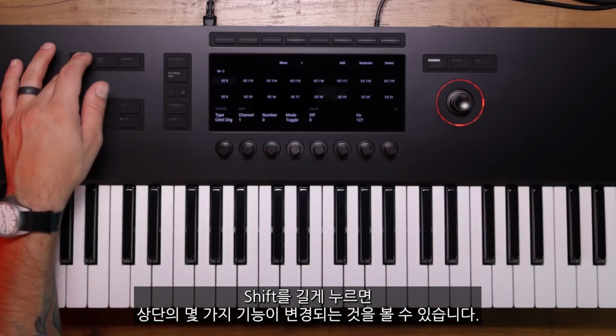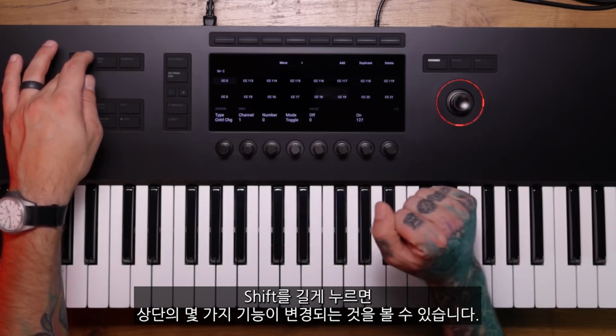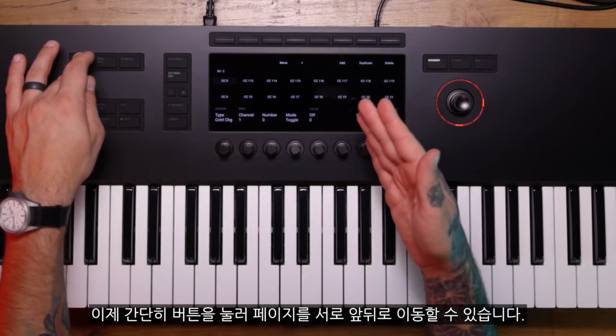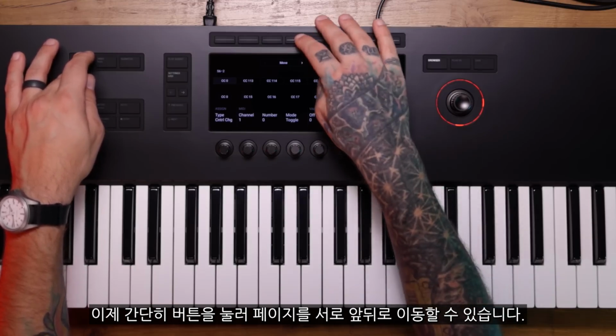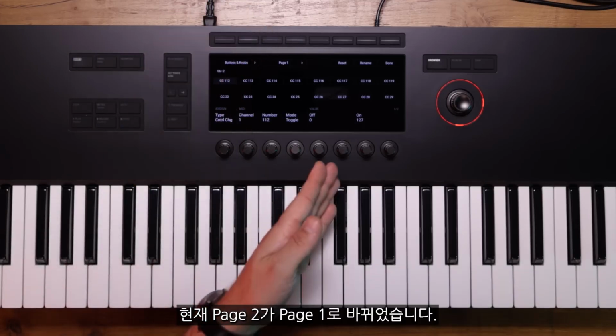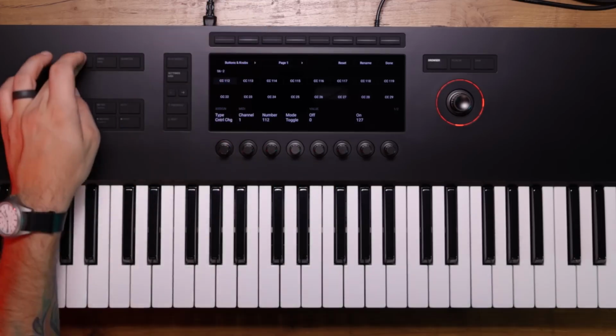Let's go ahead and hold Shift, and you're going to see some of these functions up here change, such as this one. It goes from page to move. And now we can move our pages before or after one another by simply clicking the button here. Now we just moved page 1 to page 2, and we can flip between them. That's page 2 on page 1 now. They flipped around.